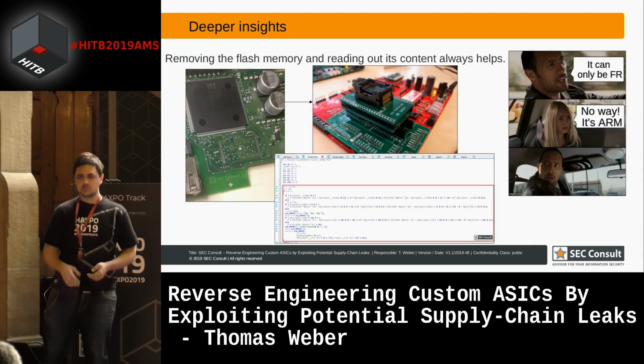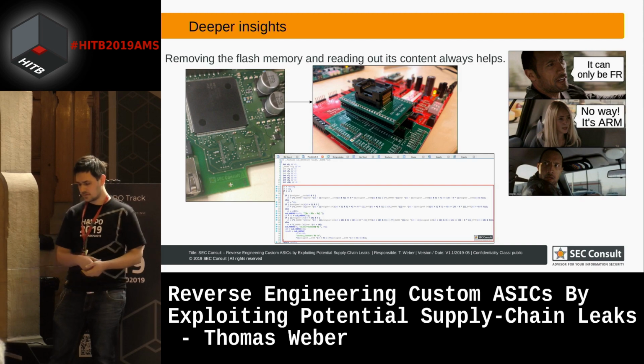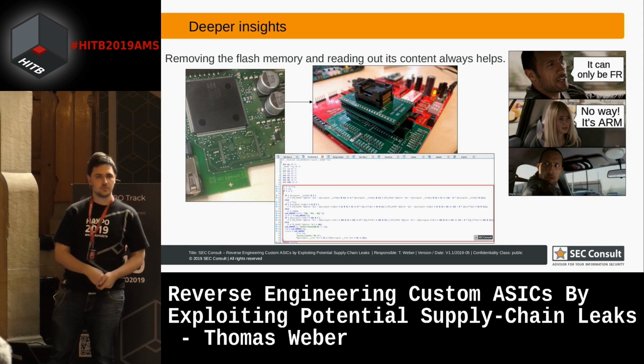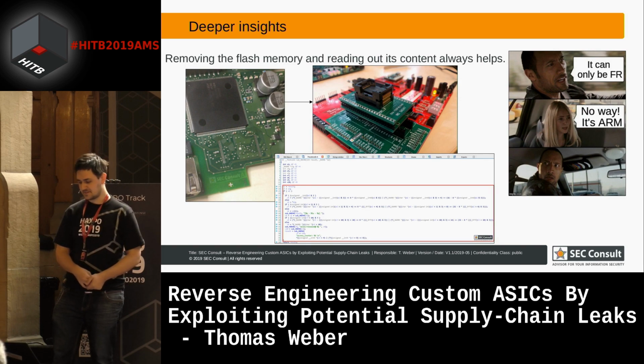And to be sure, I just removed the flash memory, used a custom solution to read the flash memory, and then I thought, okay, it's Fujitsu RISC, because when I loaded it into IDA Pro and set it to Fujitsu RISC, it looked like some multiple functions. But just one of the pins of my reader was not connected. After fixing that, I saw, okay, it's ARM.